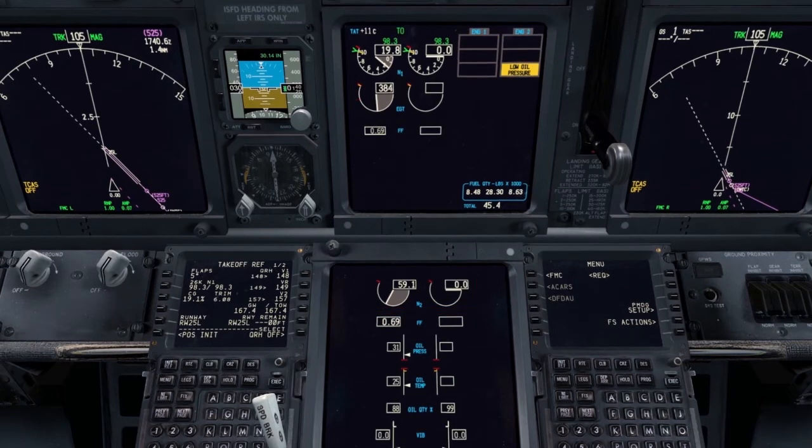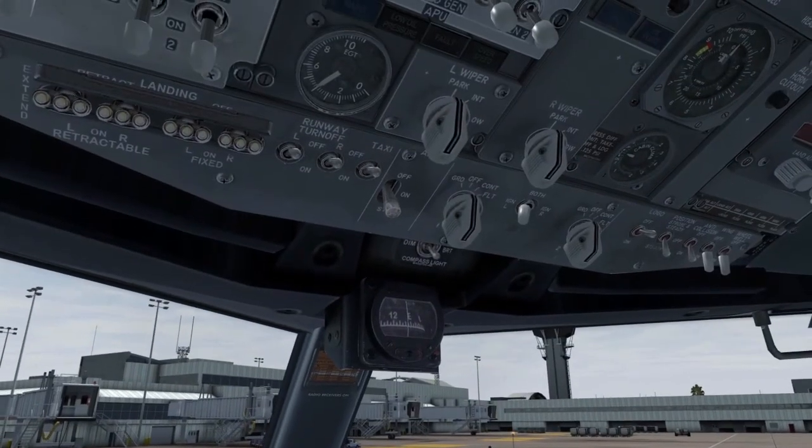The ignition system supplies sparks to light the fuel in the combustion chambers. There are 2 ignition systems per engine, a right ignition system powered by the AC standby bus, and a left igniter powered by the related AC transfer bus. Only one igniter is necessary in order to perform an engine start, but this redundancy makes the start more efficient. There is an ignition selector switch that may select either ignition L, ignition R, or ignition both. AC buses are comprehensively discussed in the 737NG electric system lesson.